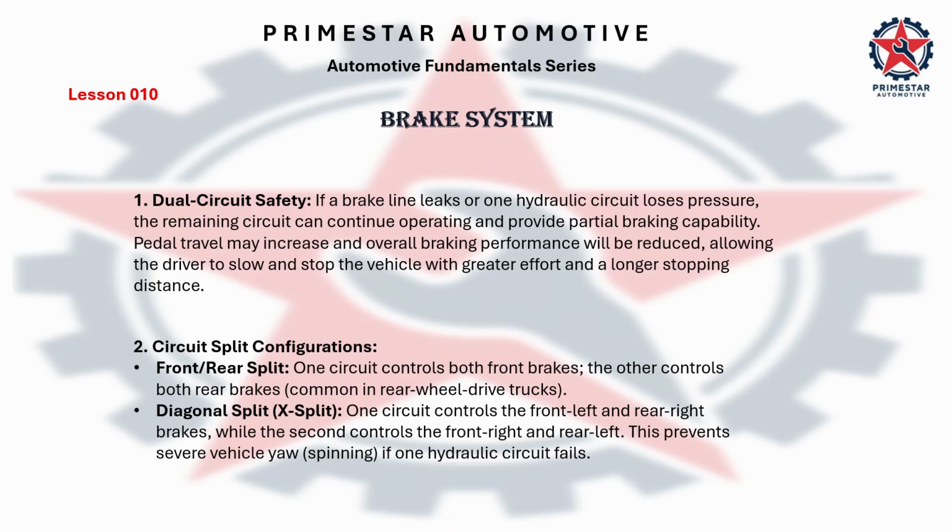Circuit split configurations. Front/rear split: one circuit controls both front brakes, the other controls both rear brakes. Common in rear-wheel drive trucks. Diagonal split or X-split: one circuit controls the front left and rear right brakes, while the second controls the front right and the rear left. This prevents severe vehicle yaw or spinning if one hydraulic circuit fails.